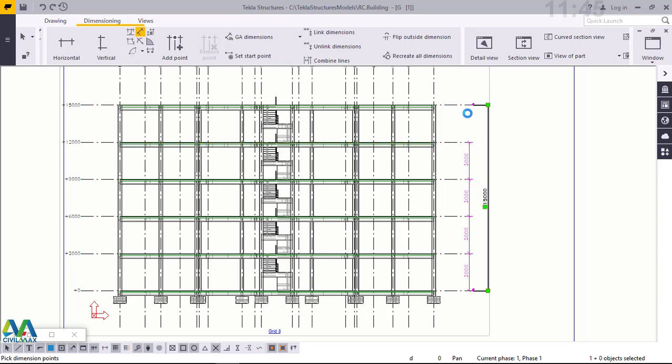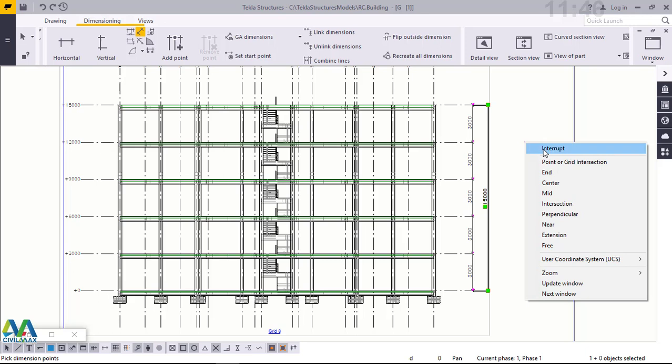Now I'll click on that spot again, then hover my cursor to the next spot I want to place my dimension. I'll snap on that spot. Then I'll go back to my initial point just to make that dimension appear, or to wind up on the command. Then I'll come to my initial spot and hover my cursor on that same spot. So the moment that square box appears, please click. There we are. Right click and exit from that dimensioning command.